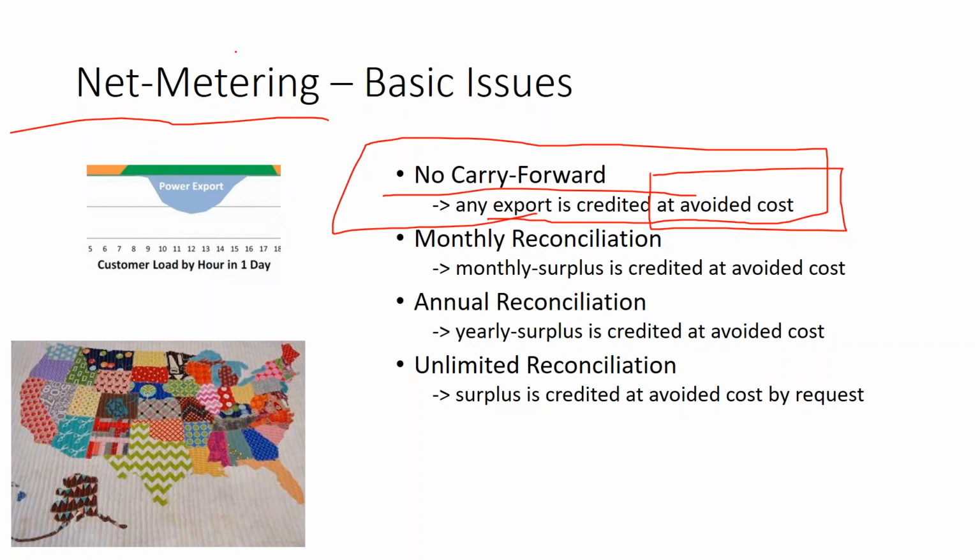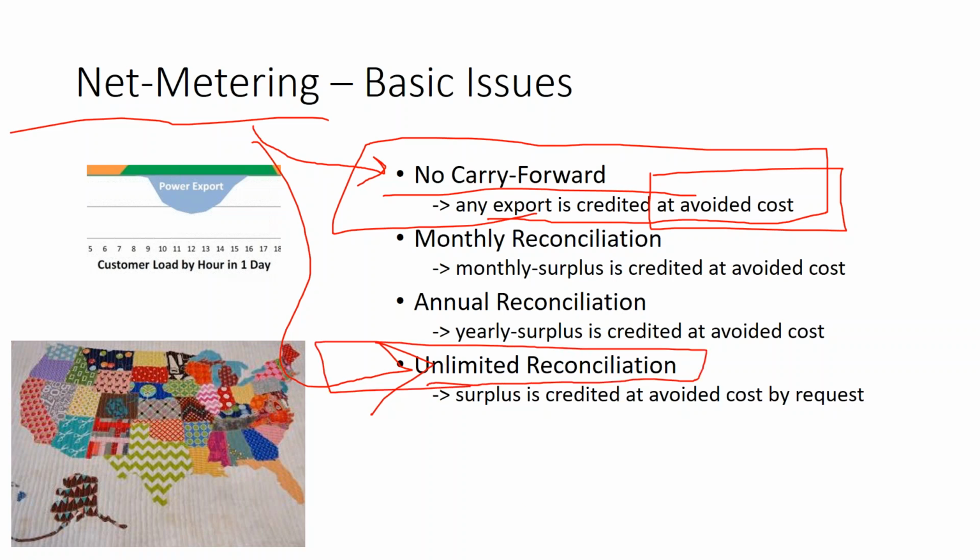And so, I think if utilities come too hard down on net metering and have no net metering, that's not the right answer. Although on the other hand, unlimited net metering, while the solar industry and the solar customer would really love that, it generates problems. With unlimited net metering, there's a few problems you might not immediately think about, but one of the big gripes is that I could outflow onto the grid in the springtime and the fall when the electricity really isn't valuable or needed, and I get a credit that will show up in the winter or the summer when the price of electricity is higher and that electricity is therefore more valuable. And so the utilities look at these unlimited net metering plans and they're completely justified in saying, now wait a minute, that's a little too extreme.